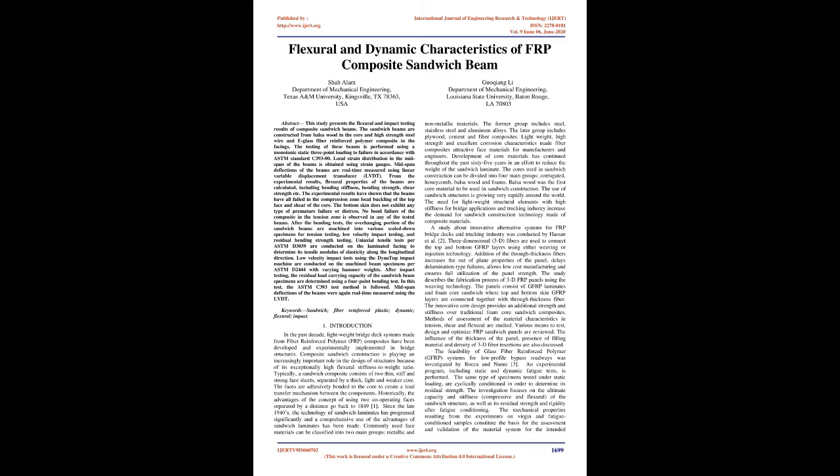After impact testing, the residual load carrying capacity of the sandwich beam specimens are determined using a 4-point bending test. In this test, the ASTM C393 test method is followed. Midspan deflections of the beams were again real-time measured using the LVDT. Keywords: sandwich, fiber reinforced plastic, dynamic, flexural, impact.